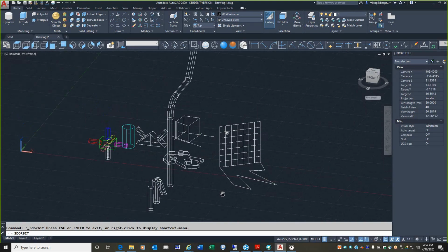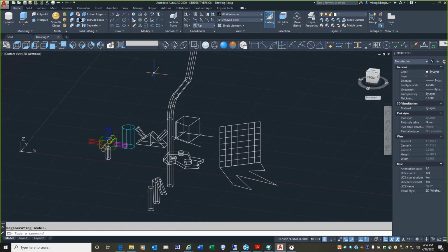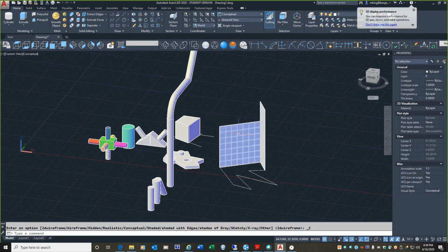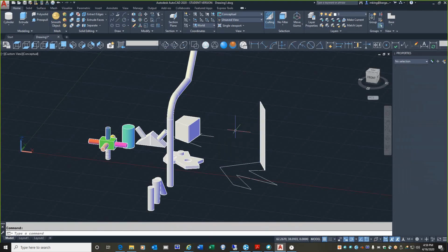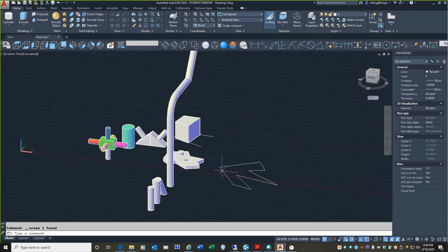If you extrude, or even press pull, I don't think it can press pull a line. Let me try that. I've never needed to do that, but I'm going to click press pull and select this line. Yeah, the same thing happens, so it'll let you do that. If you see any vertical surface that looks like that, you did something wrong. It's not a solid, and you can't put holes in it. You can't do anything to change that. This is like an object that you're stuck with. Although if you hit shade, it looks like a solid, but it's really a two-dimensional shape. It's got height and width, but no thickness. So make sure that this would be one solid shape.